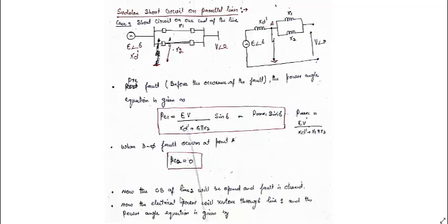Now the circuit breaker of the line 2 will operate and the line 2 will be open, that is this, and the fault is cleared. Definitely when the fault is at this point, which we have assumed, this circuit breaker will open the line. Now the electrical power will be restored through line 1. There will be some power supplied to this infinite bus through this line 1.